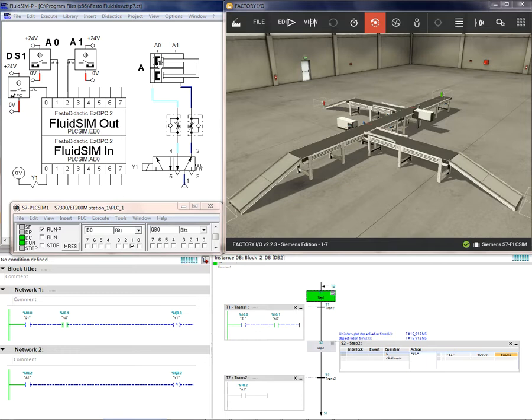The condition is, if this piston in the cylinder is in the A0 position and the operator pushes the push button S1, the piston goes out, and after it reaches the A1 sensor, it automatically gets back and goes down. The equation is Y equals A plus, A minus.